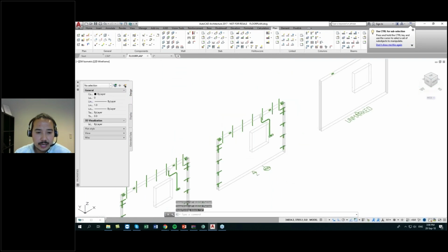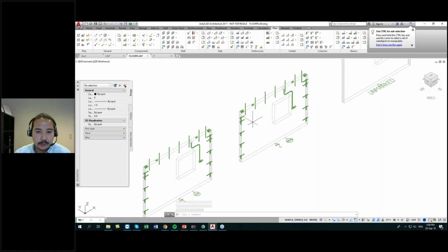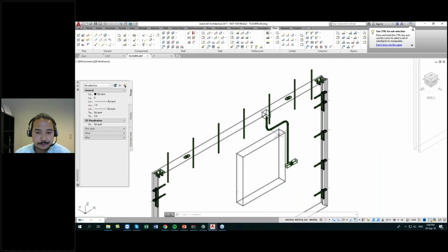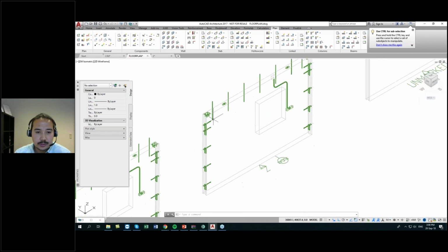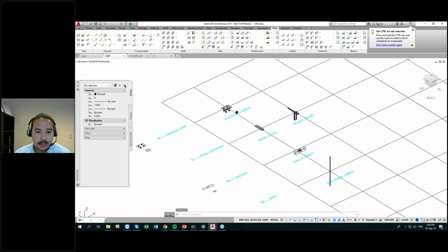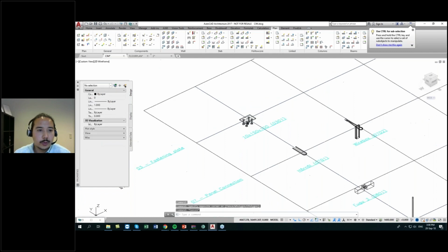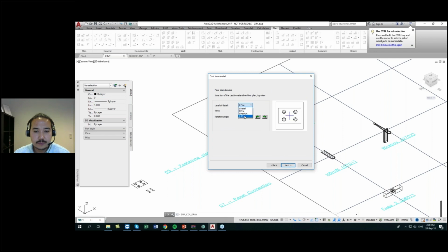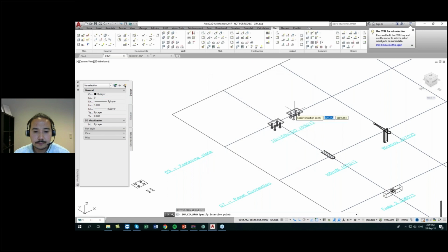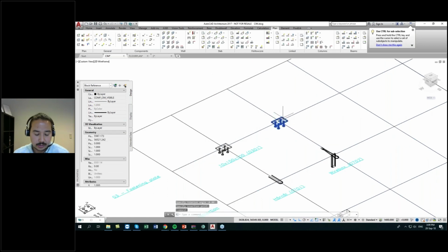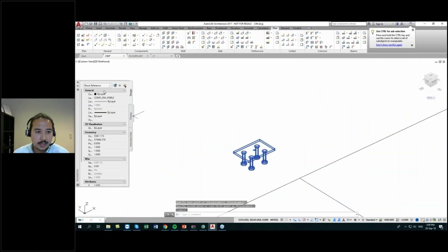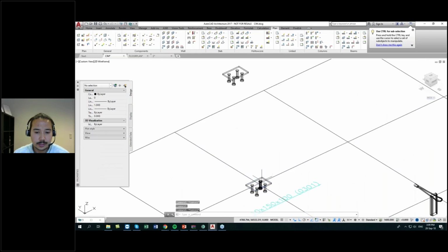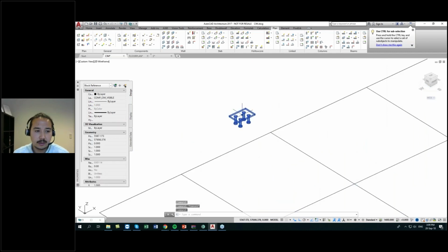So this is actually pretty much the same element now, but let's say we found out that these plates here need to be changed, and we need to make a new custom material. What we can do is either take a copy of this one and modify it, or go in and say I want to draw my custom material. I want to find the fastening plate that is this one here. This doesn't matter. I want to see it in 3D like this, and then just put it up here. As we can see now, this is a block reference. This was what I was talking about earlier. This one here is 3D solids, so I can select each part of it. This one here would get everything selected.